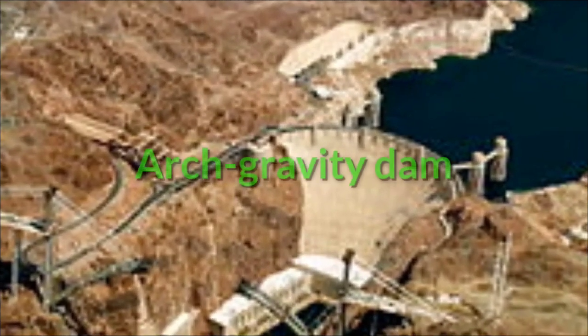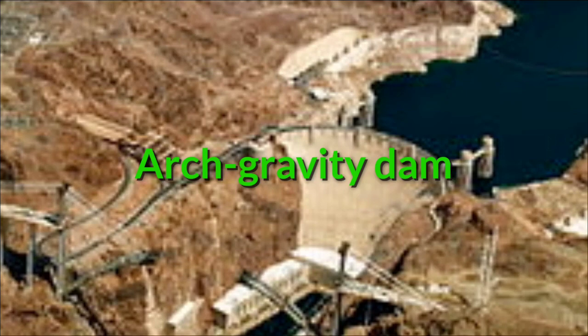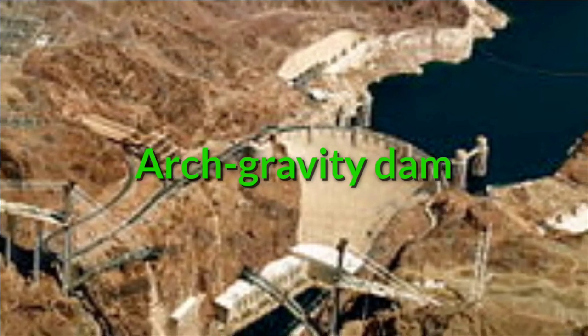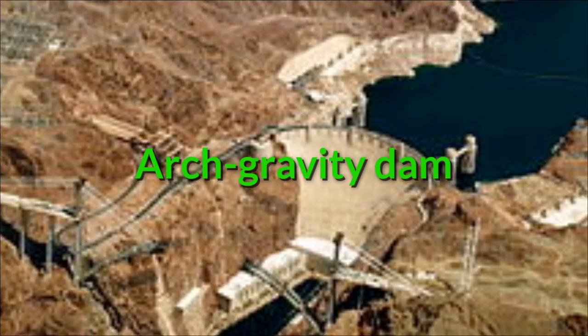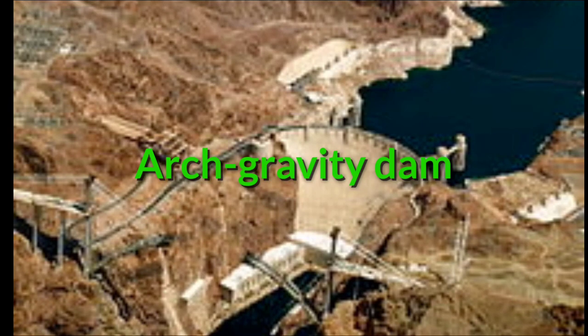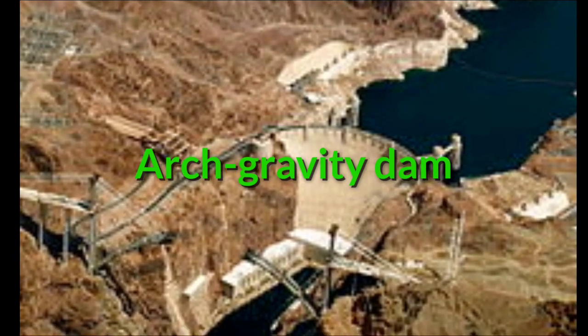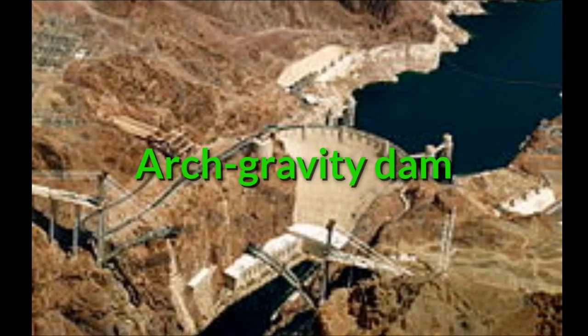Next is the arched gravity dam, which has the characteristics of both an arch dam and a gravity dam. The dam curves upstream in a narrowing shape that directs most of the water pressure against the rock walls, providing the force to compress the dam. It combines the strength of two common dams and is considered a compromise between the two.